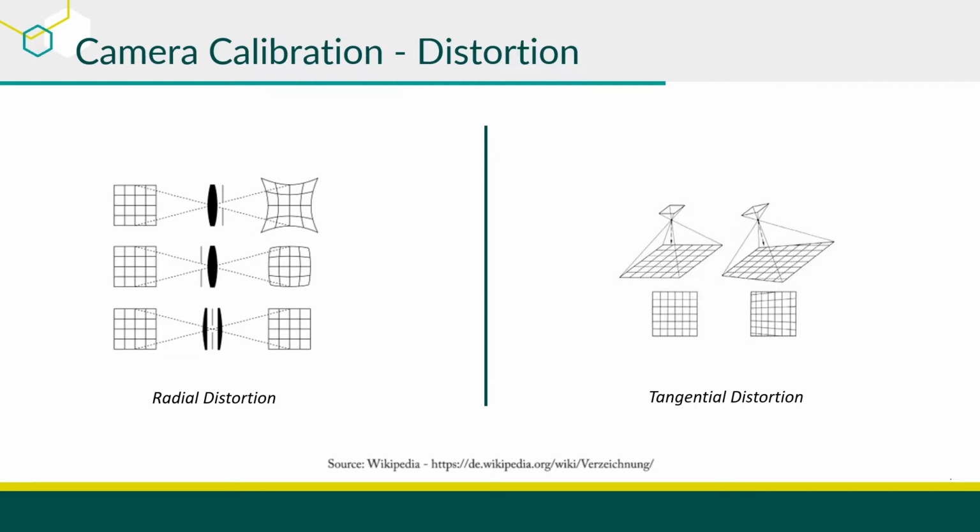Both distortions are due to the camera's internal inaccuracies, and they affect the imaging of the objects, and thus add inaccuracies to contour extraction. With the help of the camera calibration process, we can eliminate or greatly reduce both internal inaccuracies. The calibration process generates an XML file. We will refer to it as the camera calibration file. This file will allow ContourTrace to correct the camera's internal distortions when provided to the calibration operator. Now, let us see how we can generate the camera calibration file.